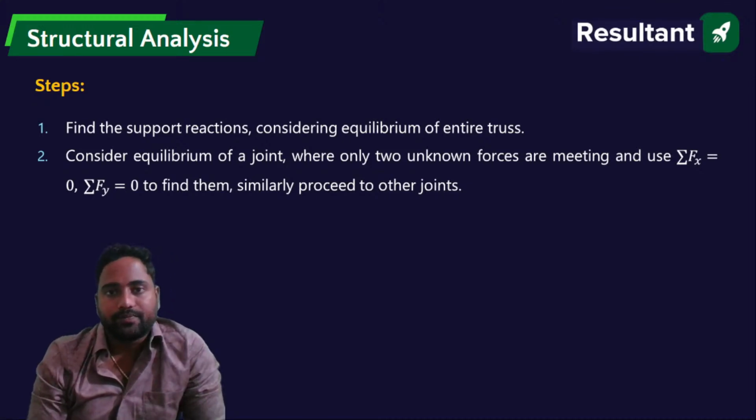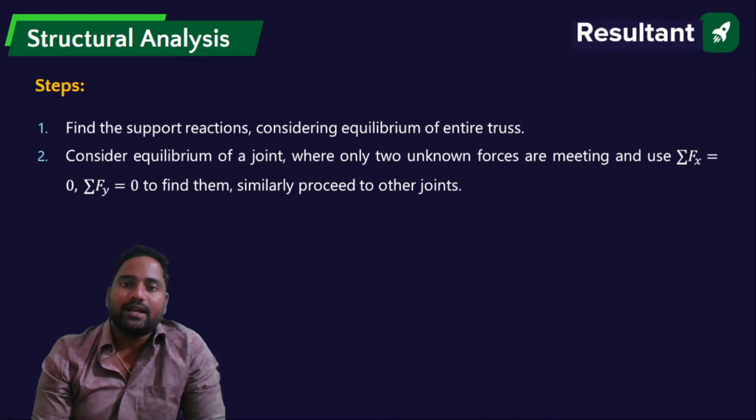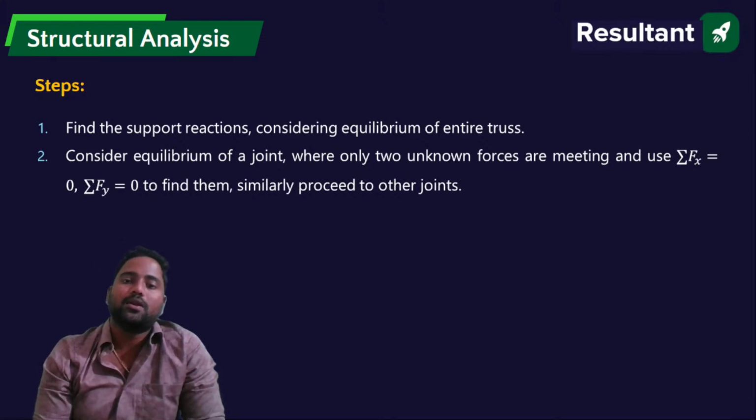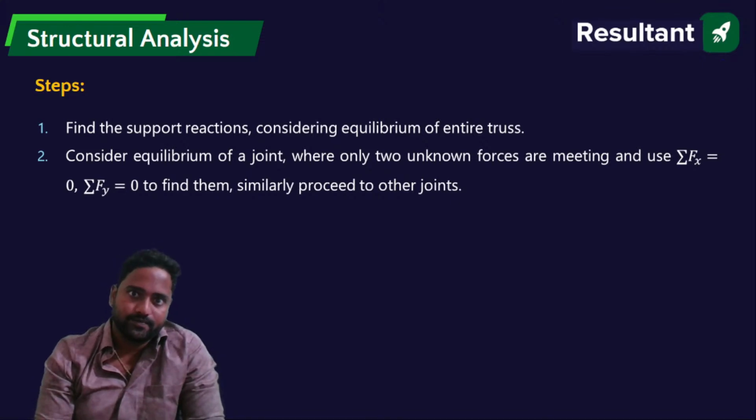So what are the steps in finding forces by using method of joints? First, we will find out the support reactions by considering equilibrium of entire truss.